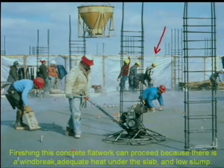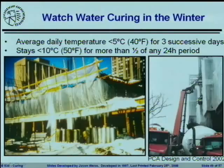Here you can see a windbreak constructed in the background. Here they are finishing the concrete on a cool day. What they're actually doing is heating the floor below, so the heat is going through the concrete, coming up through the surface, and they can use the windbreak and the heat under the slab to be able to place this during the wintertime.